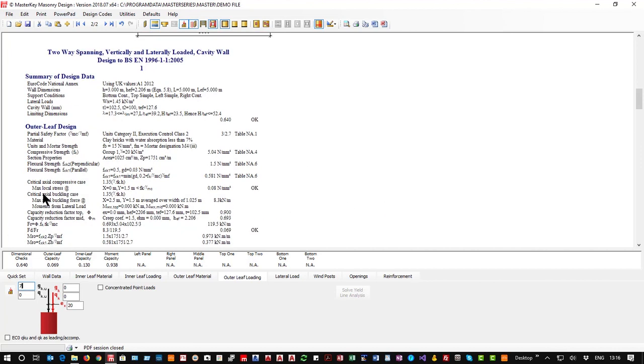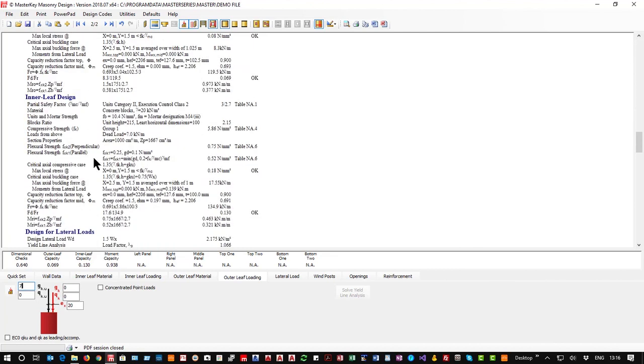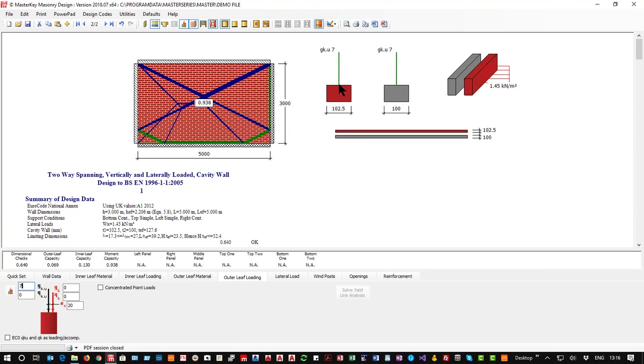And we also do consider the axial load to have a buckling consequence. So we're checking this axial load that we introduced, does it cause a buckling of the wall? So we're actually checking that as well. And we're looking at those modified values for the inner and outer, again, the axial load. So that's putting a couple of line loads, and those line loads are concentric.